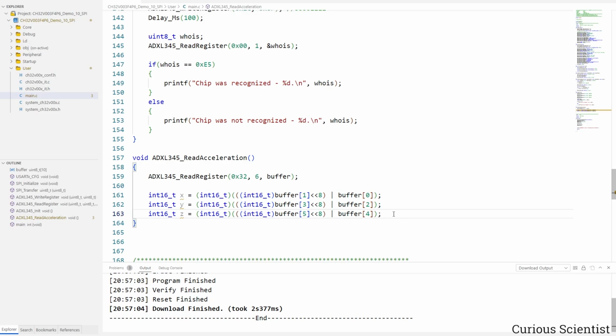These are now the raw readings of the accelerometer's AD converter, which is not super useful for us, because it would be much better if we would be able to represent these numbers in, let's say, G equivalent units. So how many times the G acceleration is experienced by the chip in these 3 axes, that would make more sense for us. But that is represented with floating point numbers. And if you followed this tutorial series from the early times, you could see that doesn't go very easily with these microcontrollers, and we have to use some tricks. So actually I will use some tricks to print the acceleration in G units in floating point numbers.